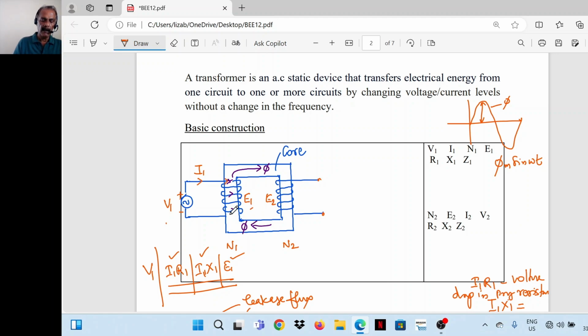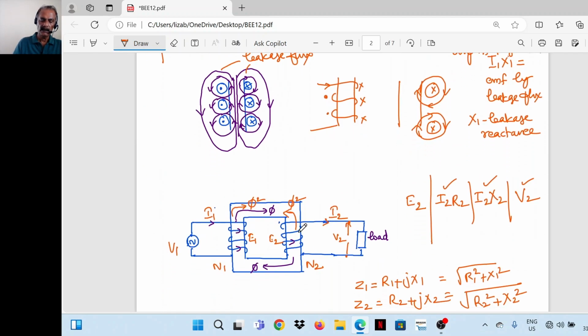Then the circulating flux induces an EMF E2 in the secondary winding. Just like the primary, the secondary winding works when current passes through it. So the secondary sets up a flux, but the primary draws a proportional current and sets up a counter flux, equal and opposite, so that it cancels out. And the flux through the core remains at the initial value always, at the no load value always.